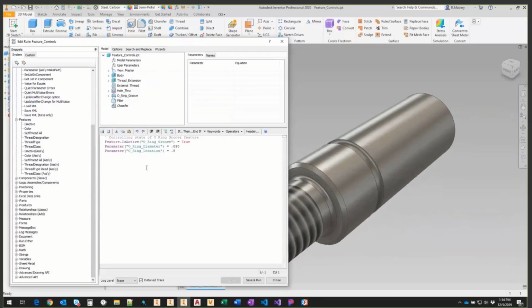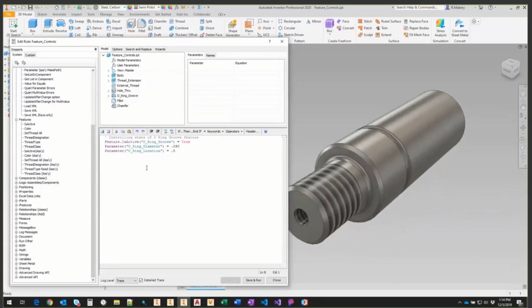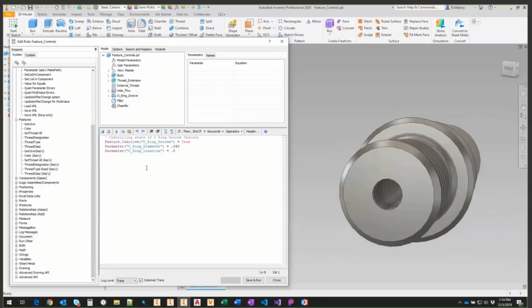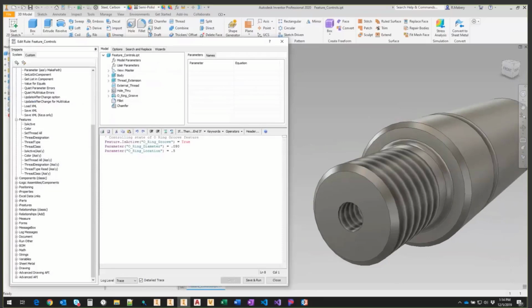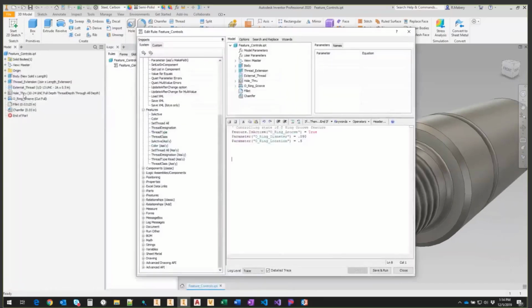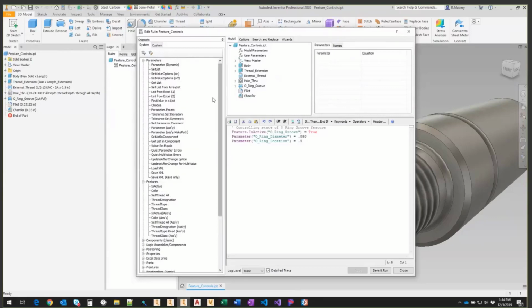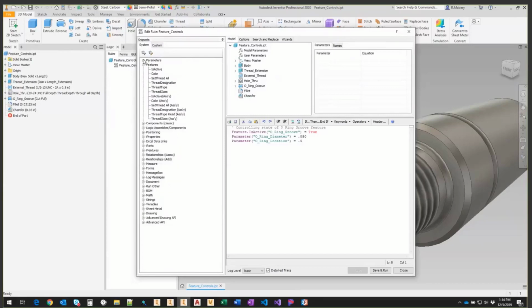If we want to talk about controlling things like the tapped hole diameter, okay, if we look at this through hole down here, it is a tapped hole. If I hover over my model browser here, we see that it's currently at 10-24 UNC full depth all the way through. Okay. I can't control that with just my parameters. That is a snippet that's inside of my features category.